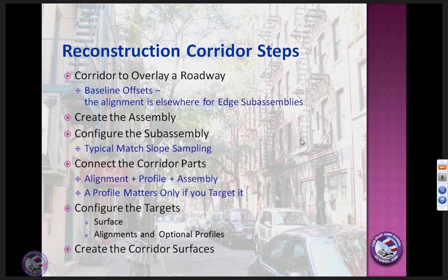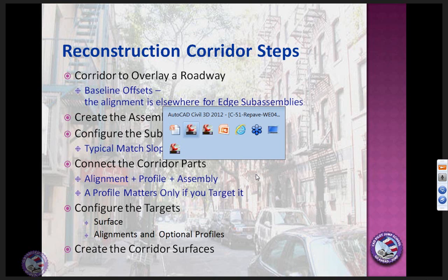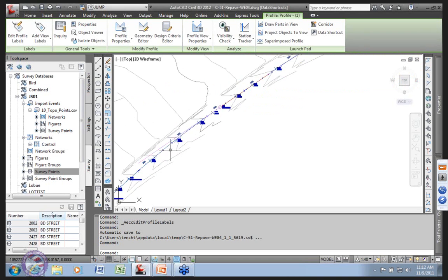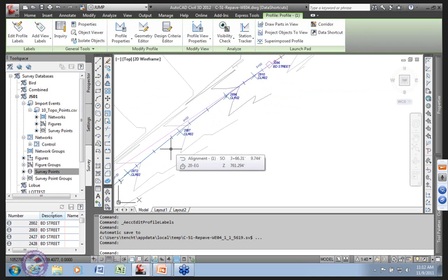Okay, so I've got in my current drawing, you saw back there, hey, I got my alignment. I now got a profile. I'm not even going to employ that profile to do anything other than create my corridor. So I could have just drawn a tangent, for example, right, and modify things later. However, I do want to make a little point here before I leave, is that this roadway actually may have super elevation applied to it.